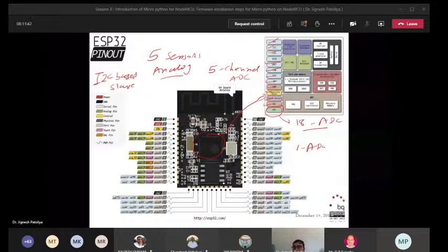Similarly, the real-time clock portion, and this AES module or cryptography hardware acceleration, is available on chip in case of ESP32, which is not available in Node MCU as well as Arduino Uno. One interesting feature of this ESP32 is that it is a 2-core microcontroller. Now, what is the use of this 2-core microcontroller?